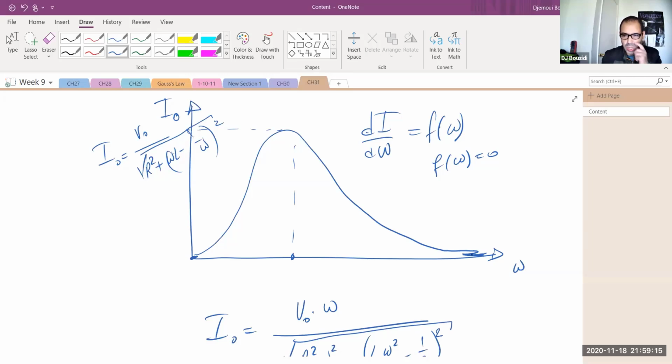So we're going to find that it's going to peak near omega naught, not exactly omega naught. So this point in here, maybe omega naught is here. It's going to be shifted by an amount that depends on R. So we're going to find where omega naught is, that I defined to be just 1 over square root of LC, by the way. We're going to find where the derivative vanishes, and we're going to find exactly where that maximum is. And from there, we're going to find the resonance, basically exactly what's going to happen. It's going to happen around omega naught.